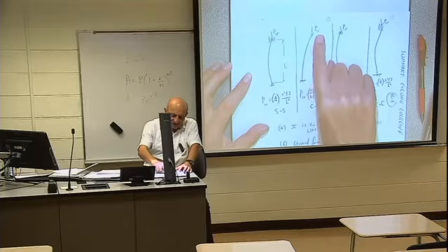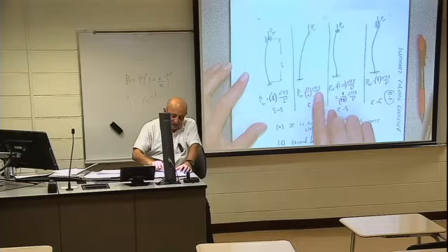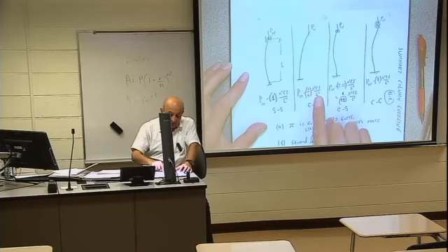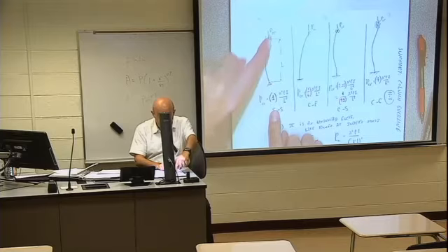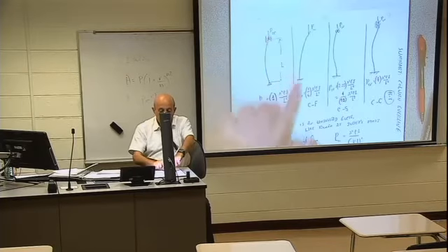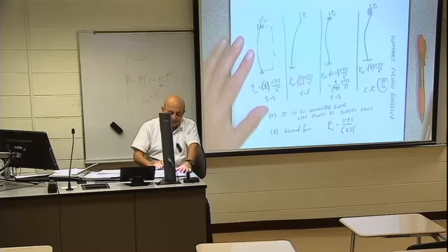For a clamped-free column, we today obtained P critical equals 1/4 times pi squared EI over L squared. That is simply supported, SS, at both ends. Simply supported here, simply supported there. Clamped here, free there. 1/4.